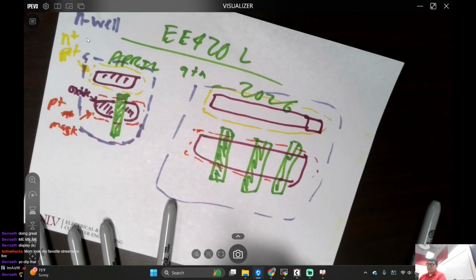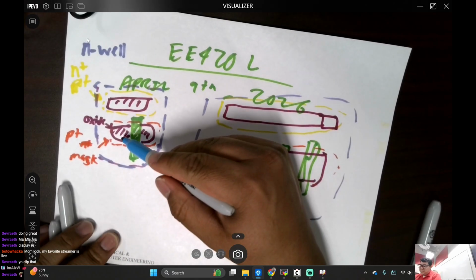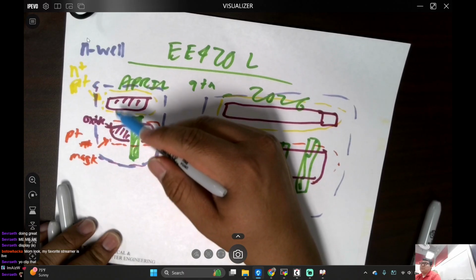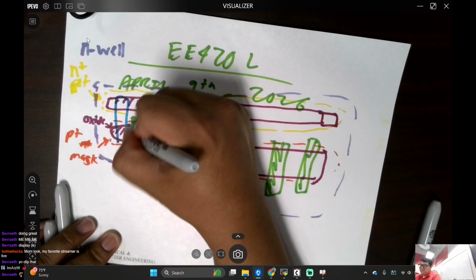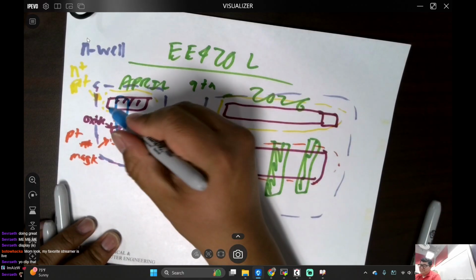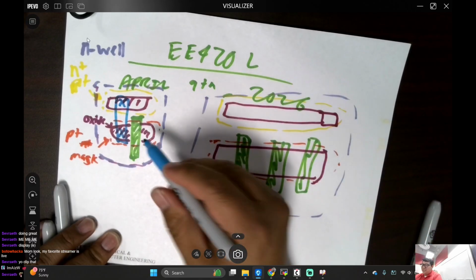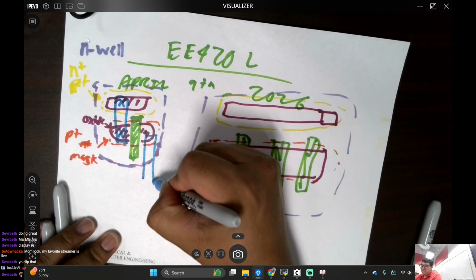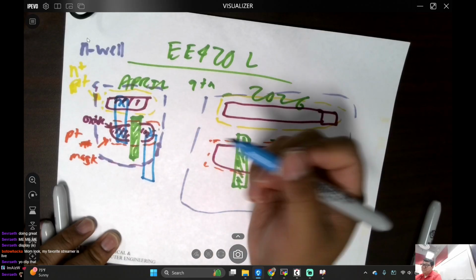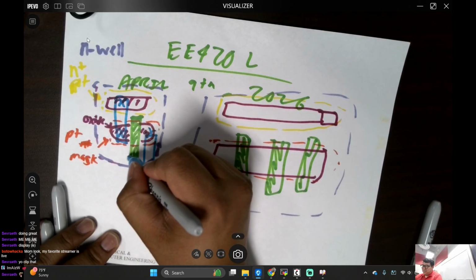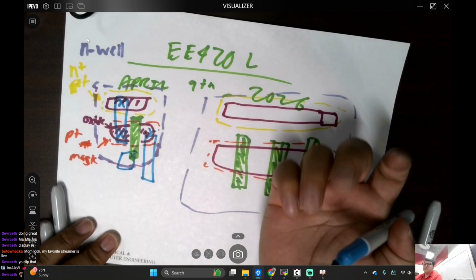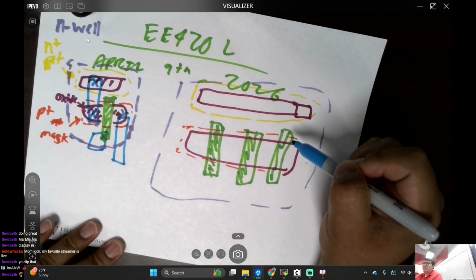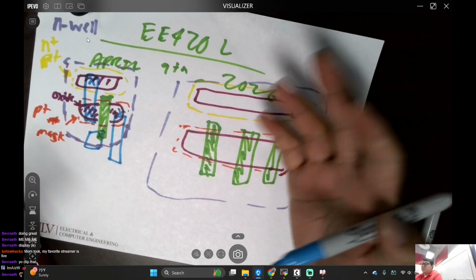Now you have this gray marker here. For this PMOS, if I want to have the source connected to the body, just that, right? Cool. Then how do I have the drain? Well, the drain just goes down here. Make sense? And then the gate, I would just tap here and go somewhere else. Make sense? Cool. So for this, let's just say it's going to be a multiplier of 5.